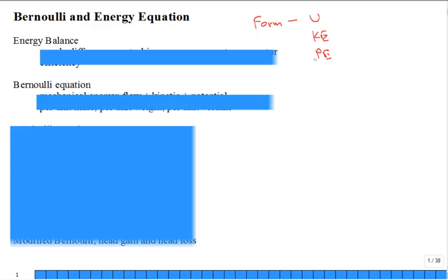And the two transfers of energy that you've been studying a lot are transfer by heat and by work, especially boundary work, shaft work, either one of those. The boundary work, WB, would be the integral of PdV, how it's pushing back the face of a piston in the expansion process, or the piston's compressing the gas or something like that.